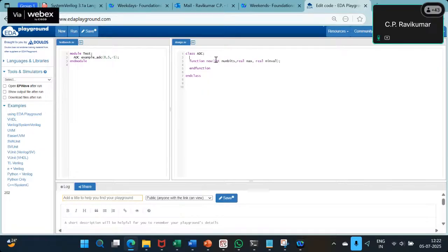If I want to be ambitious and create a SAR register, the register that I talked about, that is called a successive approximation register because it approximates the input value successively. That is, one after the other. It cannot do it right away. It may take some clock cycles for it to do.